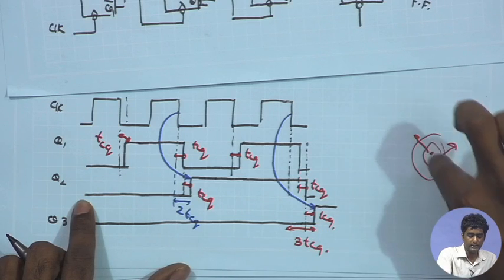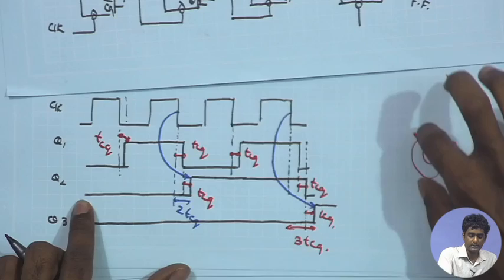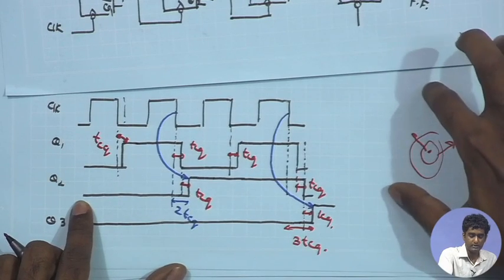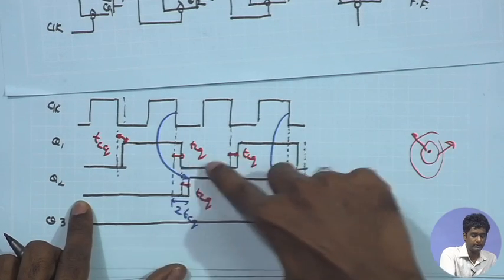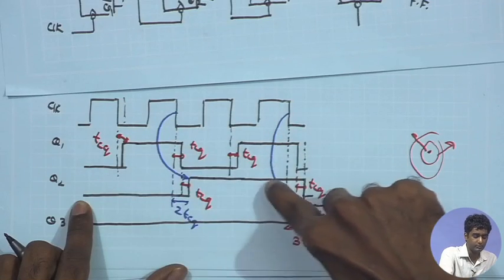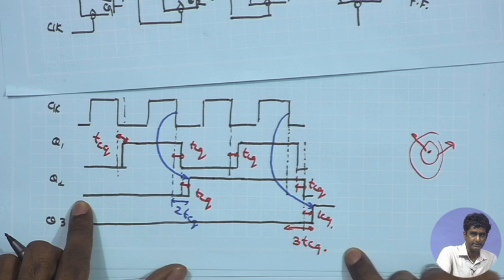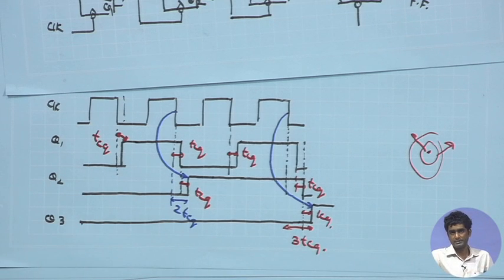So, there is a delay when you put a stone over here and the ripple generates, it is taking some time, finally step by step, and it is finally reaching the shore. So, likewise here after the negative transition of the main clock, step by step you are having these transitions after each T C Q delay, finally after n T C Q delay you are having the final output transitioning. So, this is the concept of ripple counter.